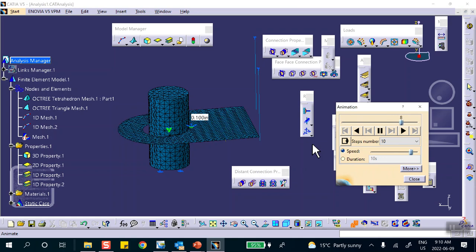Catia is not a finite element software. Buried in it is a very rudimentary, backward finite element module, which is okay for this course. So if I took this plate and loosely stuck it in there and pressurized it, it'll go a little bit down, then it hits the wall of the cylinder, and it stops. But you cannot do that in Catia. That's why I have to tell you that these are welded together.